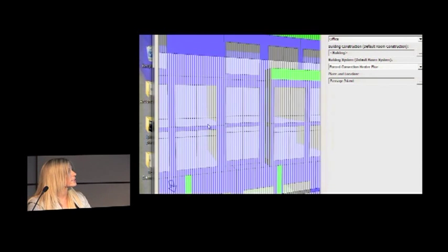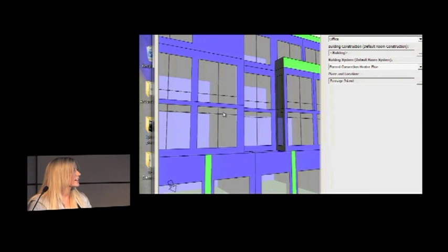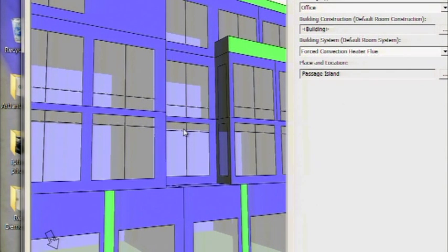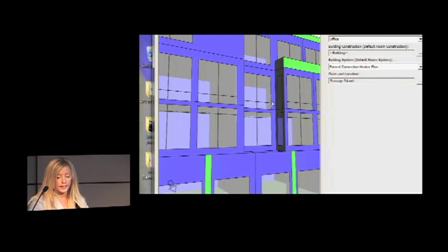The other thing you see is this is a medium-low level of complexity. We don't have the 6-sided mullions, but we still do show where they are, meaning that the windows are actually cut. So these are 4 different individual window panes with wall between them. The other thing is just adding a perpendicular shading surface that intersects it. So is that really necessary? How much is that really impacting my building? This is more than good enough to use for daylighting analysis.